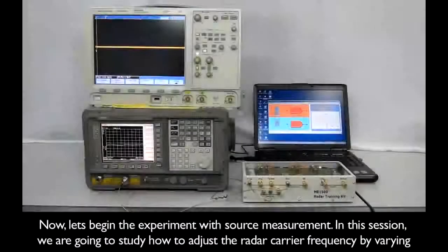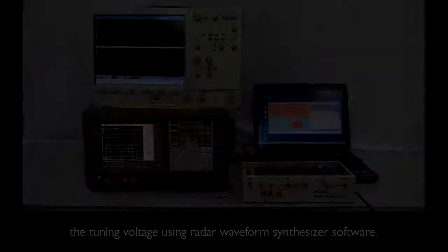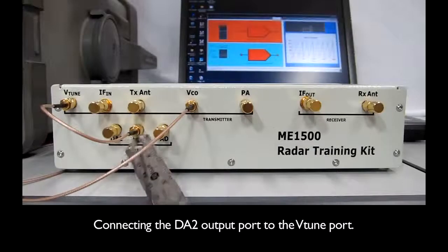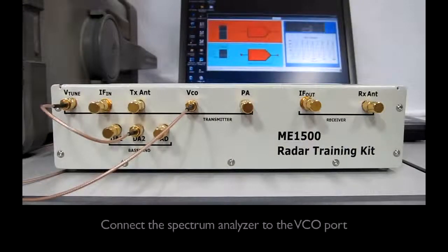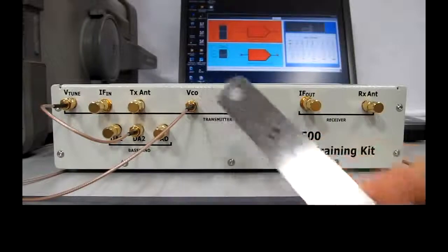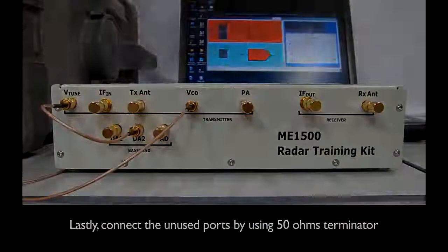Now let's begin with the experiment with source measurement. In this session, we are going to study how to adjust the radar carrier frequency by varying the tuning voltage using radar waveform synthesizer software. First, make the following connection. Connect the DA2 output port to the VTune port. Connect the spectrum analyzer to the VCO port. Lastly, connect the unused ports by using 50 ohm terminators.